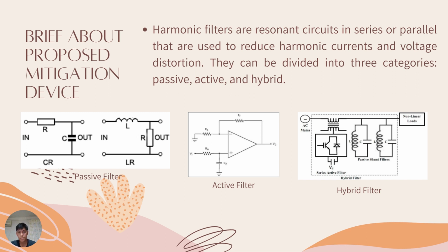Active power conditioning electronics are used by active filters to make up for undesirable harmonic currents, to specifically reduce harmonics. Active filters adjust for the deformed sinusoidal current wave. The ability of active filters to adapt to dynamic changes in the electrical distribution system is one of their advantages. Hence, because they have a stronger ability to react to significant disturbance, active filters can be taken into consideration for more intricate and crucial systems.